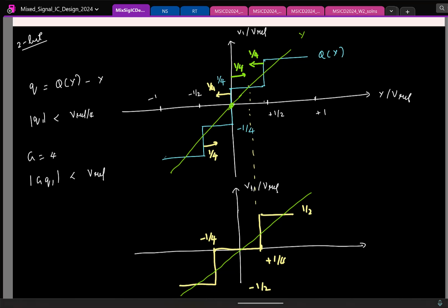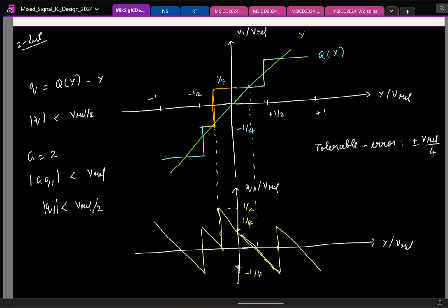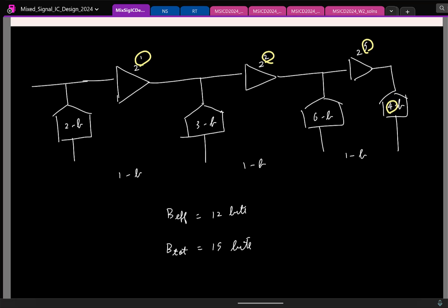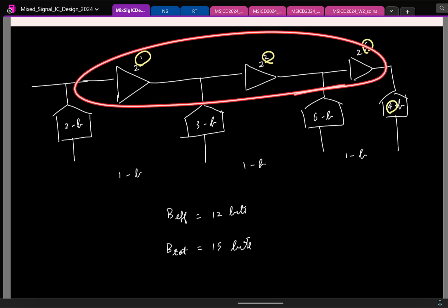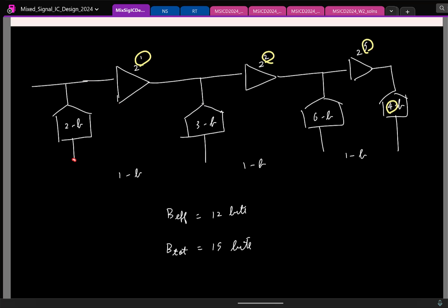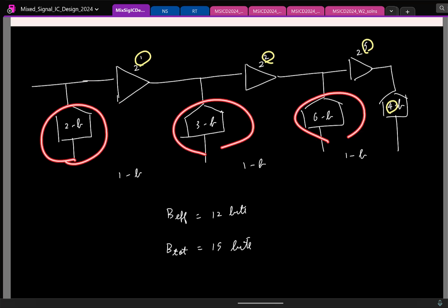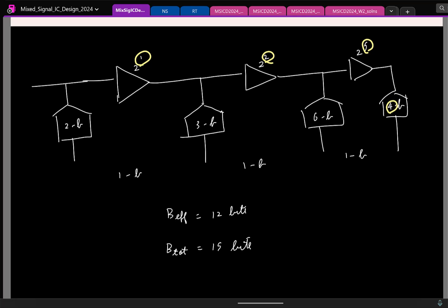And again, the thought process is the following, right? I know that in a pipeline ADC, the final resolution only depends on the last stage ADC and the gains you have. I don't really care how many comparators I use in these ADCs. This ADC resolution eventually sets a limit on the maximum gain, and you are obviously not using the maximum gain.